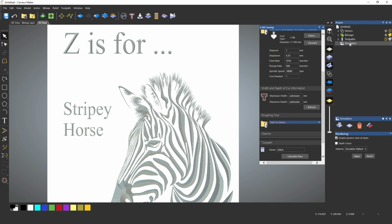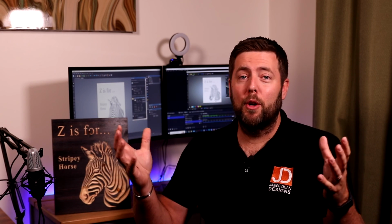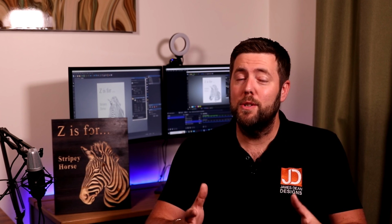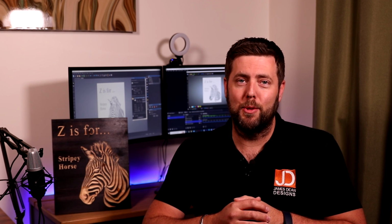And then obviously with all that done, you continue to export your toolpaths as normal. Click on the toolpaths menu, the save icon, and then save them out using the relevant format for you or your machine. And that wraps up creating our very first V-carve. Now, as you've just seen on screen, a lot of it is about playing with those settings initially to start to understand how things change and the different results. Use the simulation tool. It is one of the great features of this software, and you can start to see how things come out in real time, before moving on to actually machining your job out.